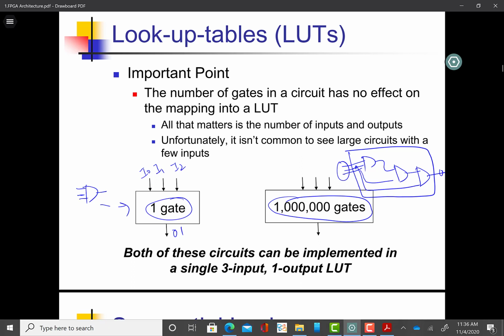So this is all about lookup tables and how they are implemented at the circuit level, how they operate in different modes, how they can be used in single output mode, and how they can be used in dual output mode. All this is very fundamental and very important for understanding what we can call the workhorse of the FPGA.